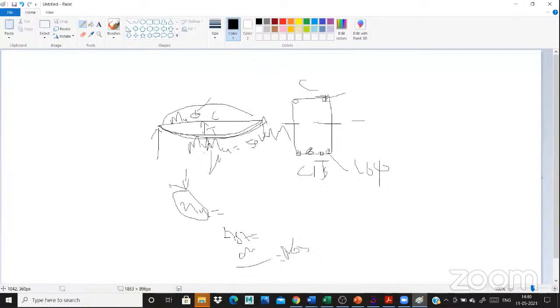Why did I provide 4 bars in the bottom zone? Because the moment is high in tension. In compression I provided only 2 hanger bars. Why? No moment in compression. That is the condition for providing reinforcement in a beam. This is for simply supported.